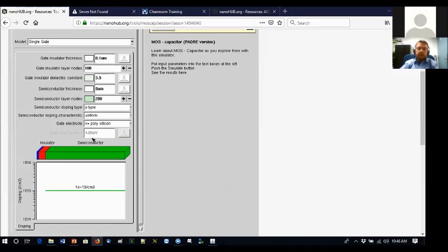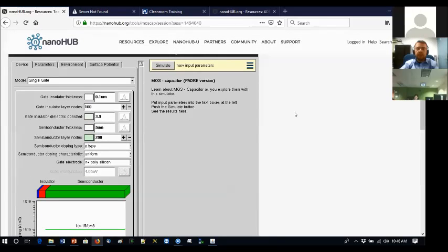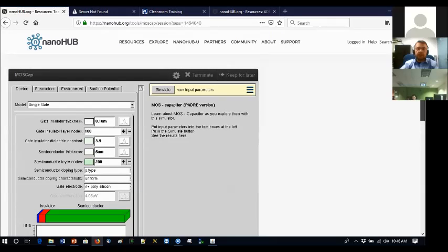Okay, so let's look at it. We have the semiconductor that's doped 10 to the 15, and it's a p-type dopant. We actually examined this configuration before. There will be banding like we examined before, and then we get the gate electrode as an N plus polysilicon, and we are looking into silicon dioxide. How do I know that? Well, the dielectric constant is given, and by experience I know that's silicon dioxide.